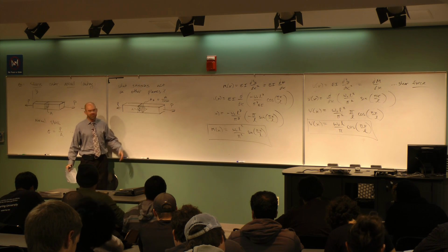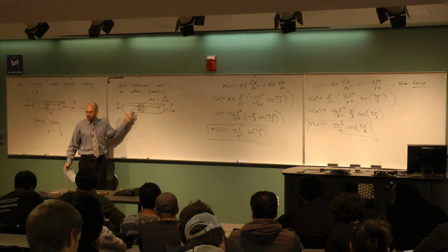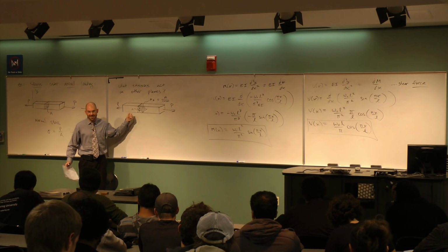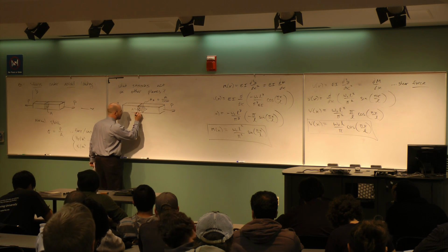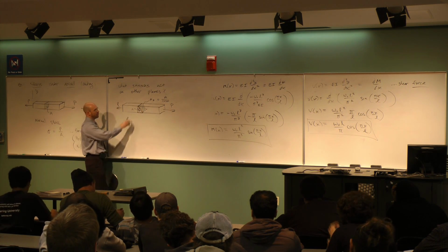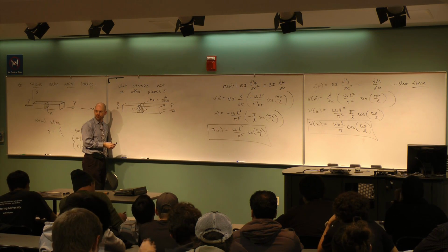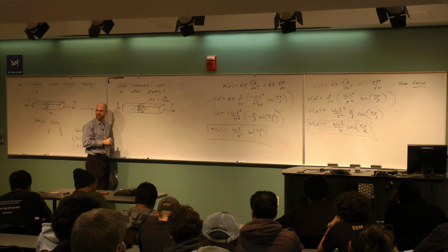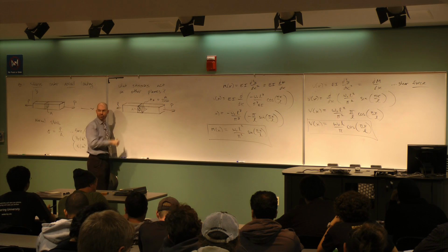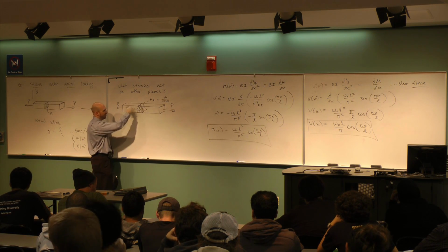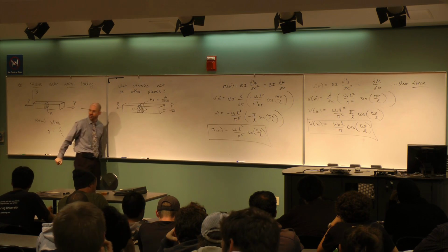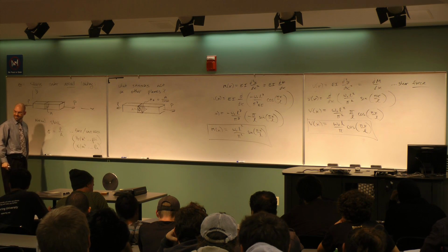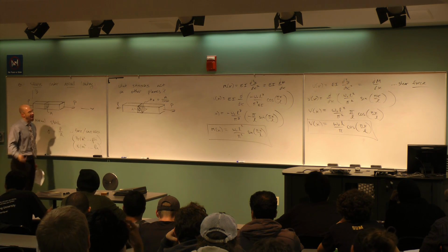By the way, does it bother anybody that I'm using areas and talking about triangles? This bothered me the first time I saw that. Are you guys okay with that? The triangle is just this front projection of it, so the lengths of these sides clearly are related by the cosine. The area is the length in the plane times the width, the thickness of the bar. So the areas are the same numbers just scaled by the thickness. That's the reason why this area scales with that area by the cosine. It goes the same way the length goes. The thickness is the same. Good with that?